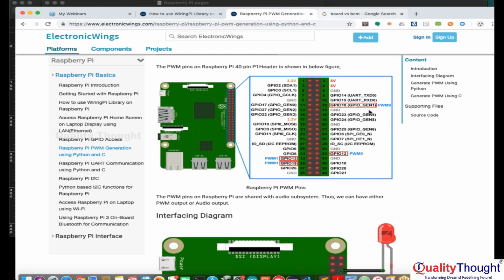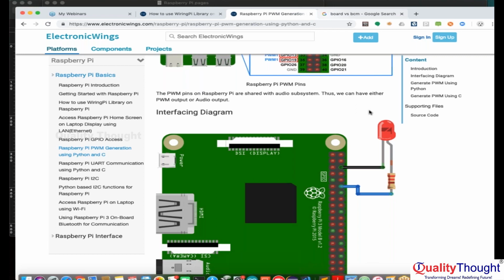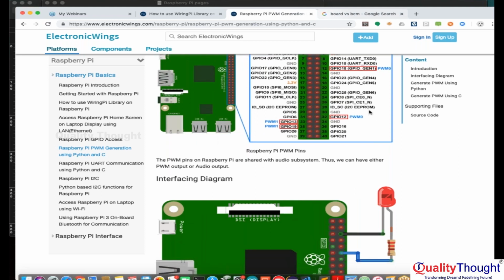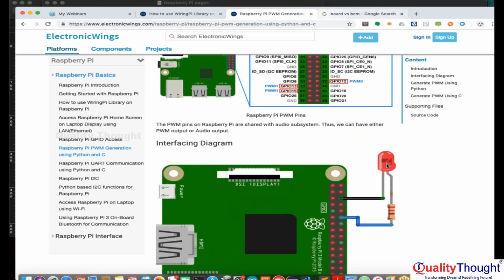So here you have to remember that PWM pins will help you provide analog outputs, or variable output, to the pins to increase and decrease the intensity of the LED. If I'm talking about intensity, it can be anything. For example, if I have to control the speed of a motor, it's the same. A PWM signal is applied there, so it does the same job for me.